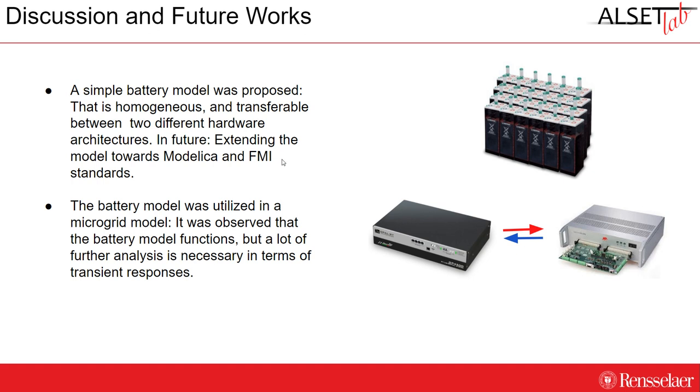Another part of the work is to test the microgrid model with the battery in it in different scenarios. We just showed a step response. We need to do different kinds of faults, loss of generation, loss of load, swing. A lot of things can be done and need to be tested. For this paper, we just showed the step response just to exhibit and demonstrate that our model can work inside a bigger model.